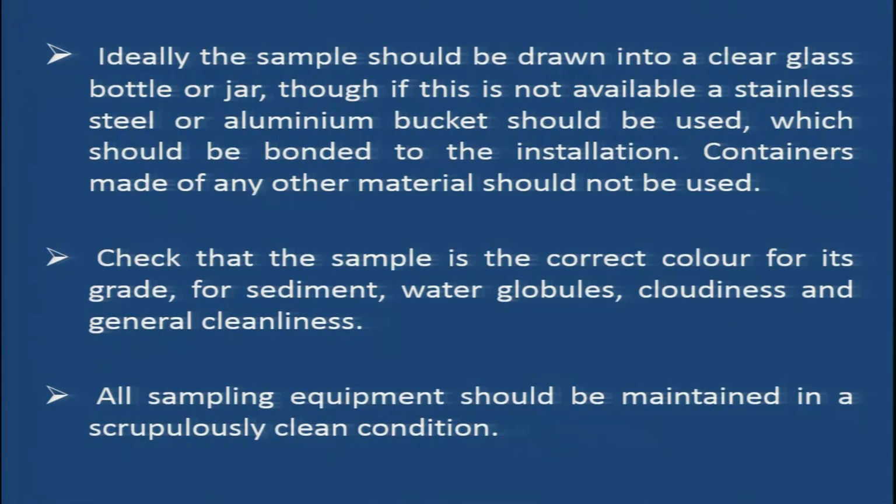Check that the sample is the correct color for its grade, and check for sediment, water globules, cloudiness, and general cleanliness. All sampling equipment should be maintained in a clean condition. So, these are the general checks, general inspections, general precautions to be followed while handling fuel.